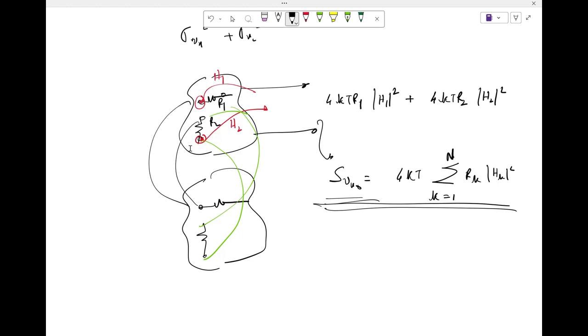Then naturally the curiosity should be how much power the other person is burning in order to reduce the noise. If I am burning twice the amount of power to get twice the SNR, then big deal, I can also do that. I can just take my circuit, copy it, connect node to node, done. Don't have to do anything. You get extra SNR. That's why SNR and power go hand in hand. Quoting one without quoting the other does not make any sense. Okay, fine. We'll stop here.